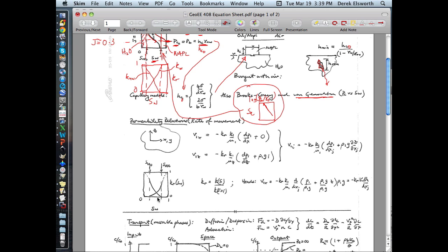We talked about ways of being able to define relative permeabilities. And we tried to make it relatively simple and basically say that you could calculate the flow velocities, the volume flow rates, as equal to, you've done this calculation, I know, total area of the core times hydraulic conductivity times relative permeability, whatever the saturation is, times head gradient, right? dH/dx.